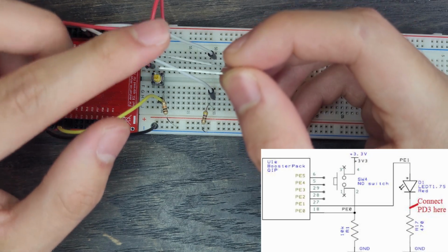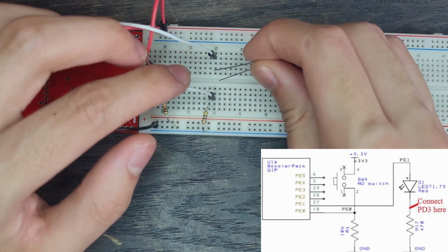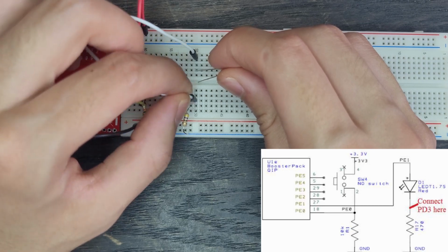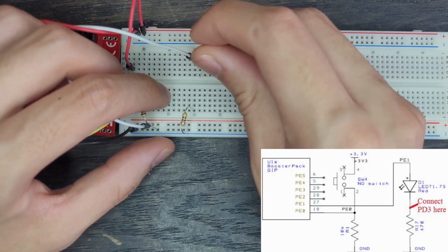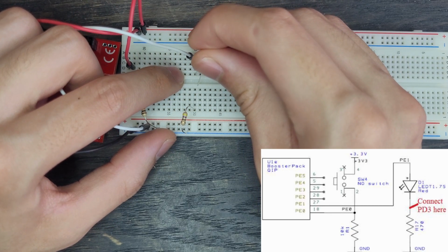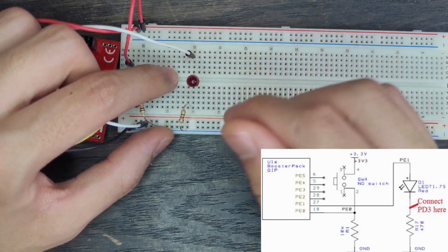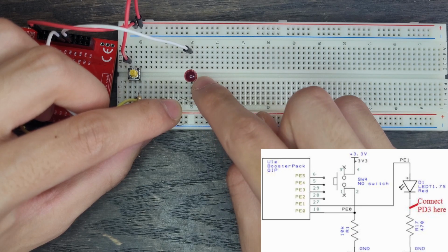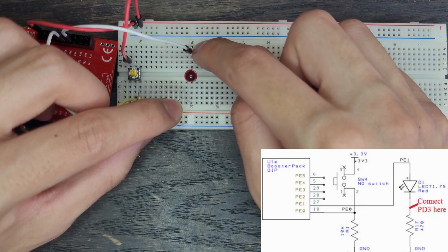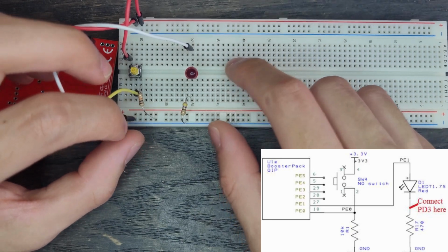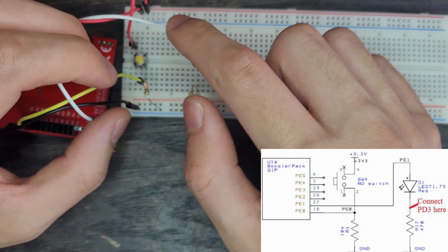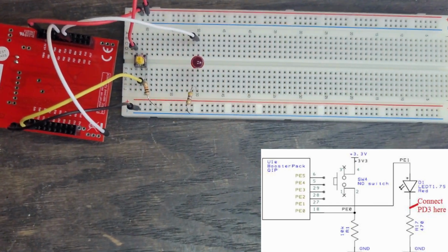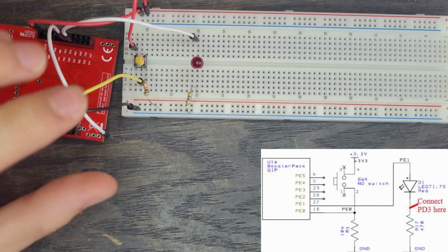We know that the anode is going to go on top, so I'm going to put it on this side of the breadboard, up here, and then I'm going to put the cathode on the other side. So anode on this top part, and the cathode on this side, that way they're not on the same column. And so that is also in the same column as our resistor, and that's in the same thing as this. That's important because we need whatever current flowing through this wire going into the LED to eventually go into ground. So that is how that would work.